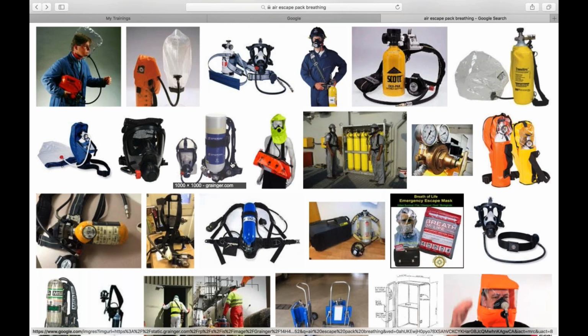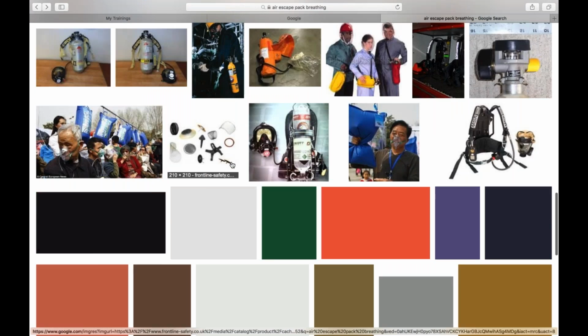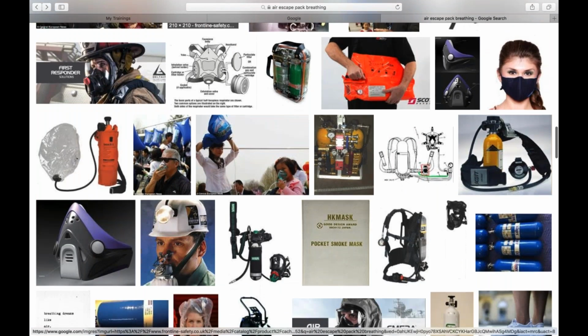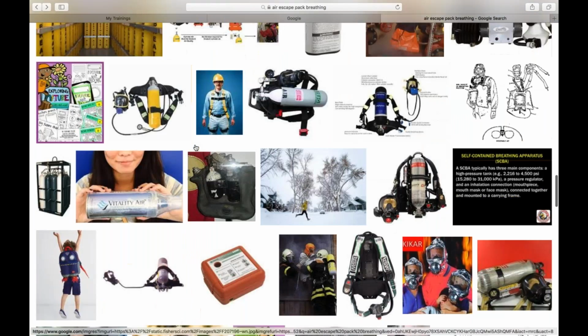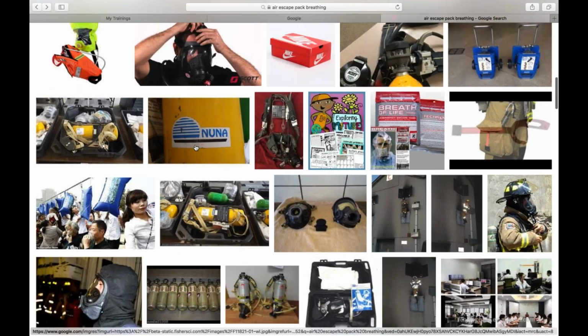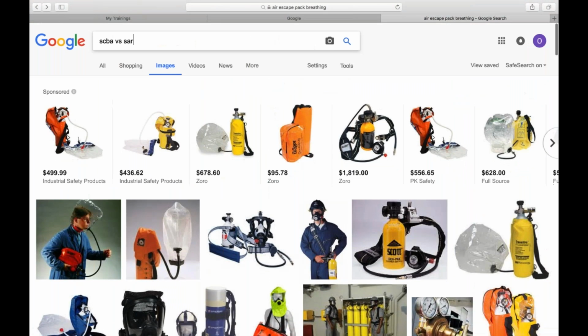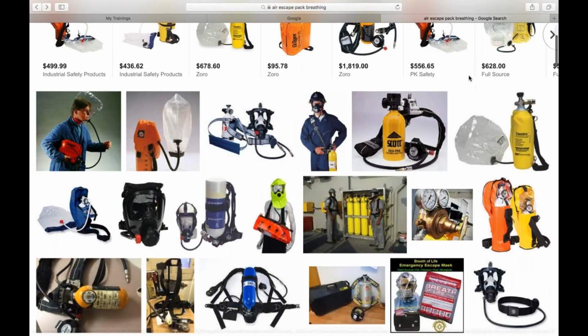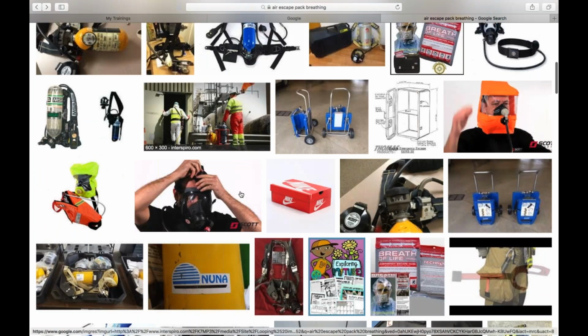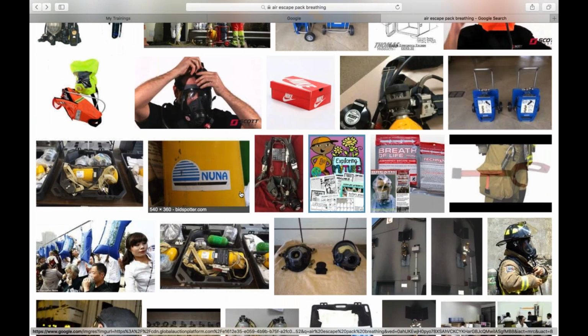SCBA, something like this, is because with the SCBA, we're carrying the air on our back, and we should be able to maintain the meter. Fireman's the best way I can explain it, okay? So we can monitor the air that's on our back, whereas with the SAR, if somebody inadvertently, and we've seen this happen before in some situations, in investigations, where employees' air has been inadvertently disconnected, the airline hose, or it's been severed or knotted, which hopefully won't happen, but it's happened. And so employees have less control, and all they have is that emergency pack to get out then.